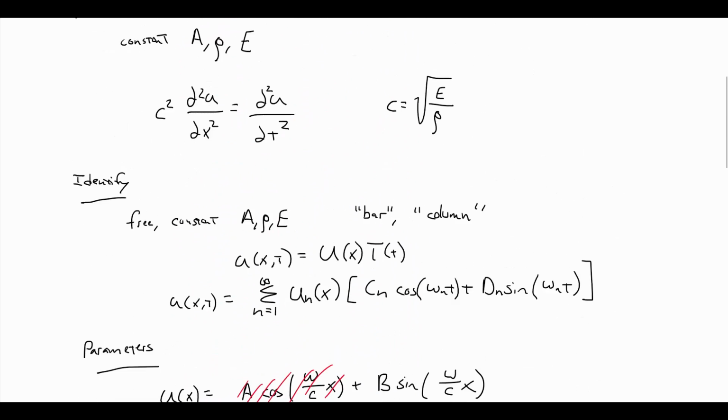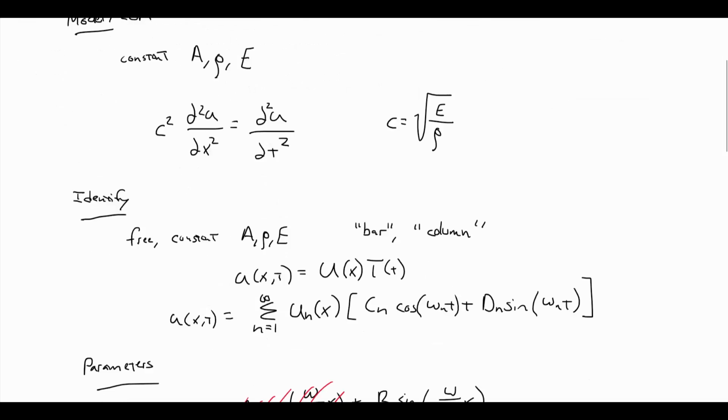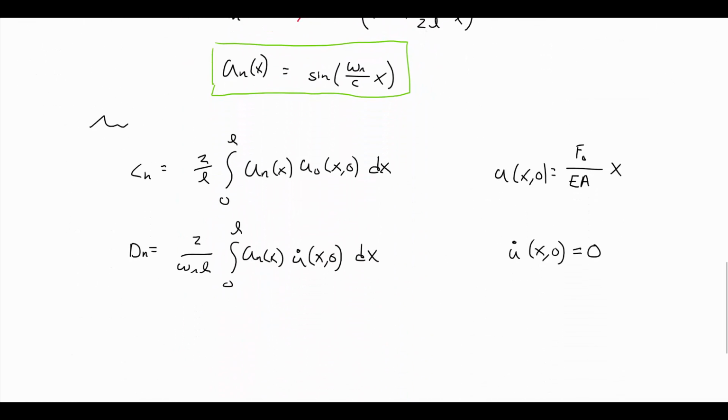And then anywhere in between, it's going to be this linearly increasing amount of deflection as we get further and further from the wall. So we don't want to say it's uniformly PL over EA, because not every point is going to deflect the same initially. It's this Px over EA, so that it is going to linearly vary.